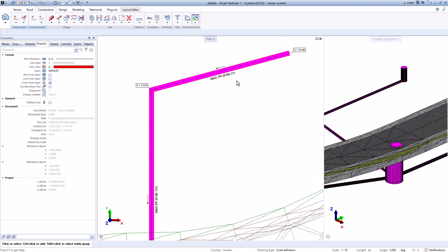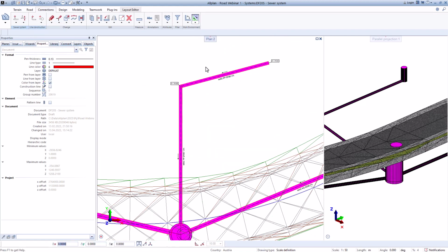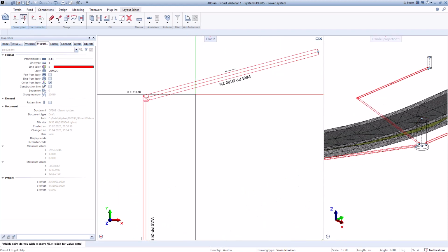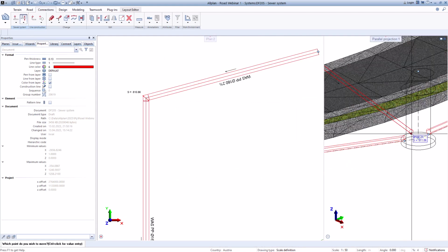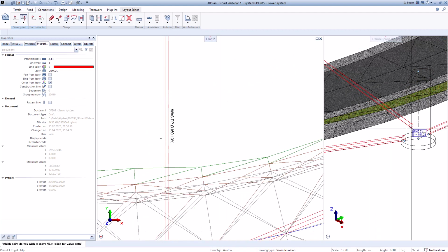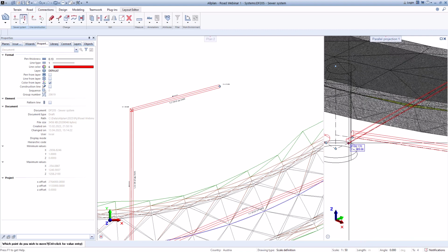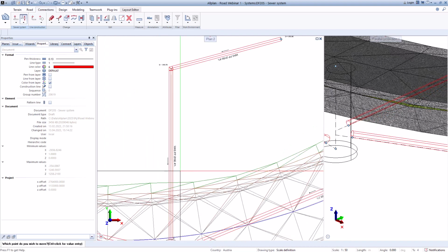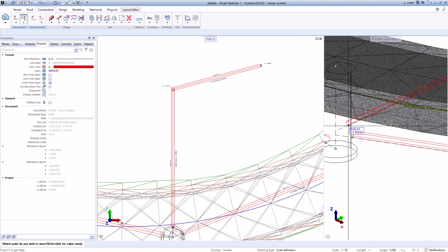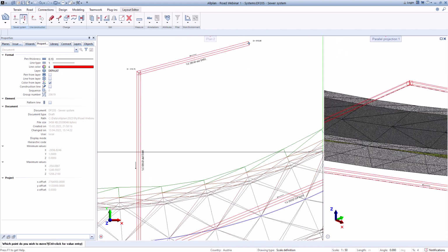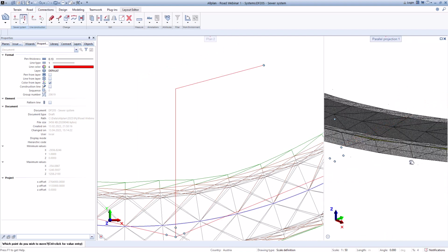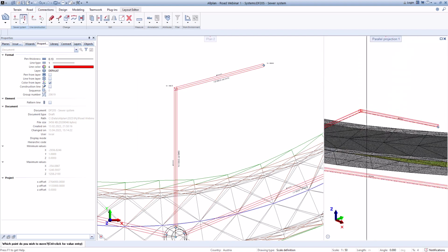You see this is 30% of inclination, but we modify the height because this inclination is too much. So you click and you bring it up, and you see here now I'm not on the correct one. I was on a different pipe, but now I moved to the right one. So you can always move; you don't have to click the function again. I moved here, and the inclination changed. Let's see.